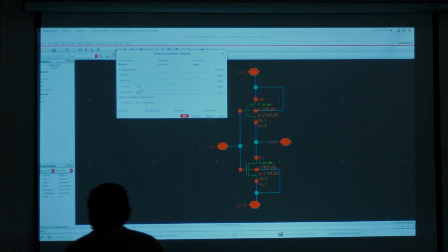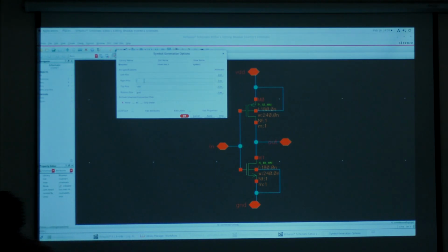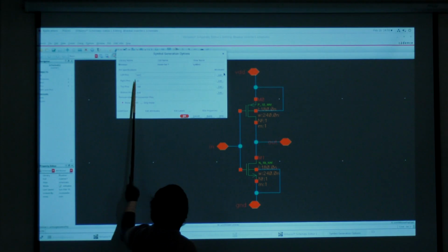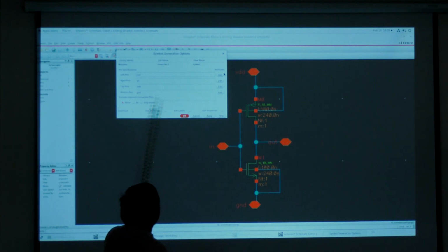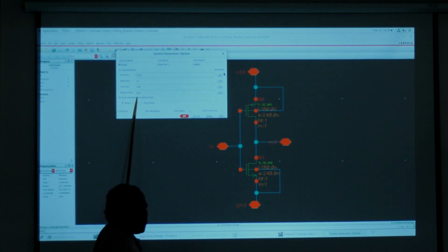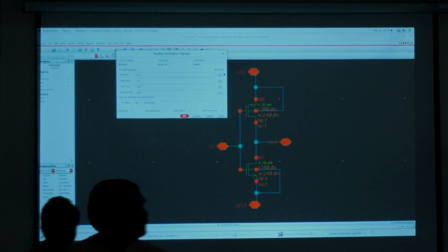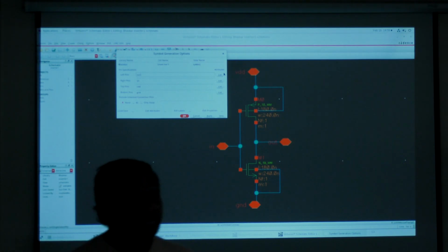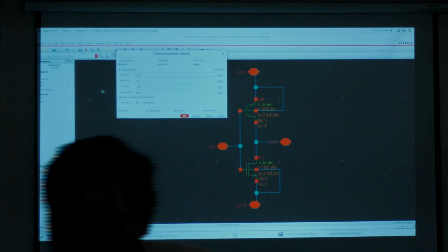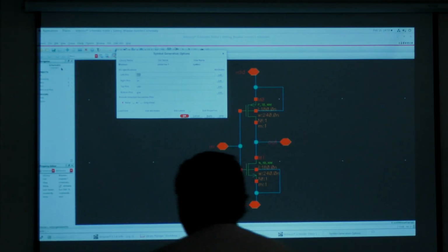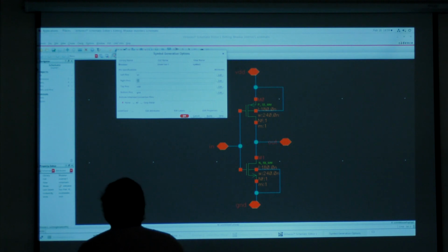Here we have the pins VDD. What are the pins that we have given in the schematic will reflect here: VDD, V in, ground and out. The placement of pins can be placed as usual. We have taken bottom as ground, on top as VDD, left as out and right as in. Placement of pins based on your necessity, you can take left as in, right as out.